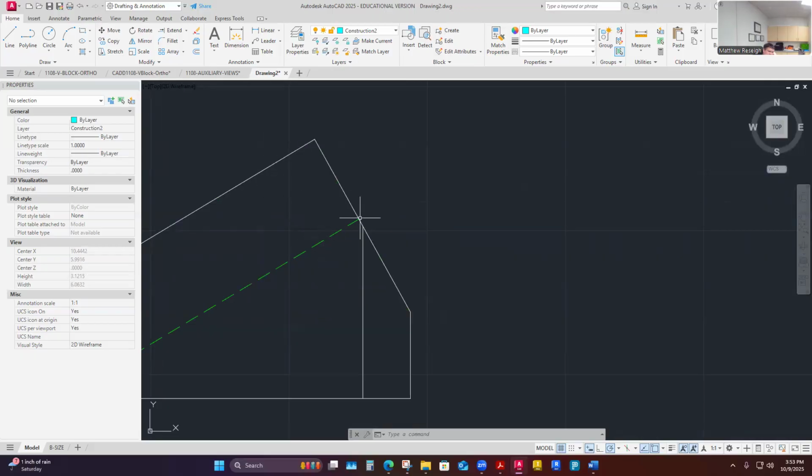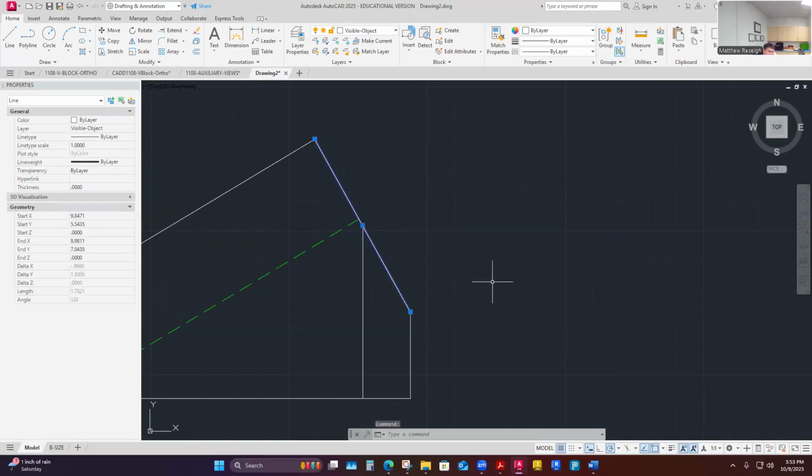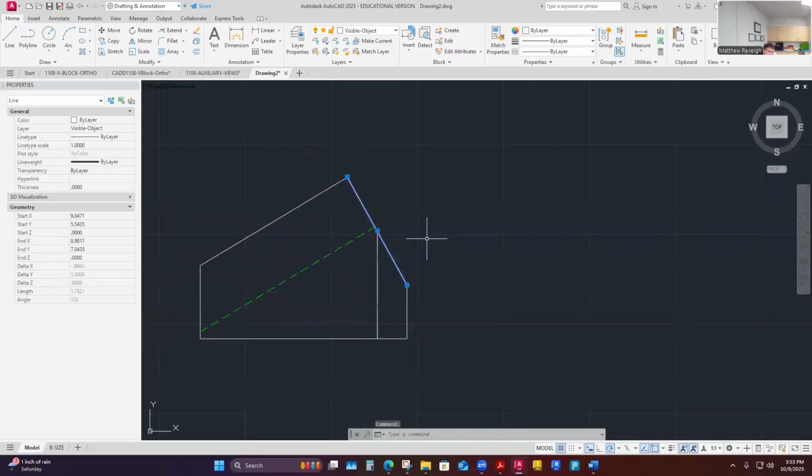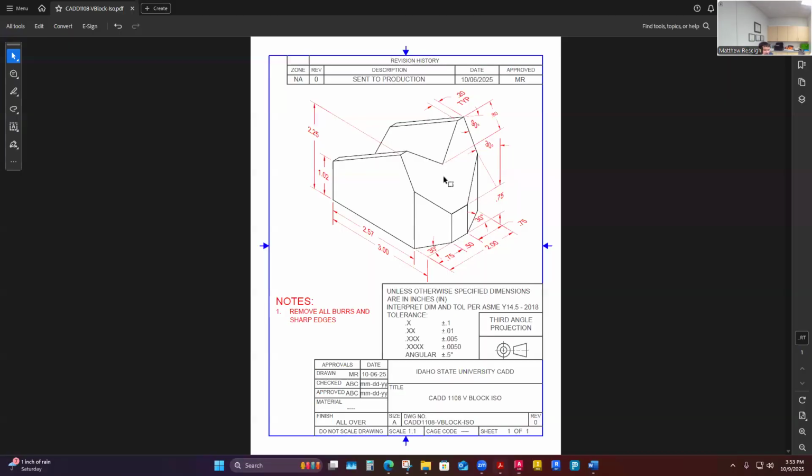What I just did is offset that, and it made me a little nervous that the point to points didn't line up when I did that, because I want to use the same concept here to develop this surface. If I can look down on it and put my eyes perpendicular to that surface, I will start to pick up true lengths. If I put my eyes on this surface, this is a true length, this is a true length, this is a true length, which I already have. And I already have that one too, but that's all right. I get those true lengths.